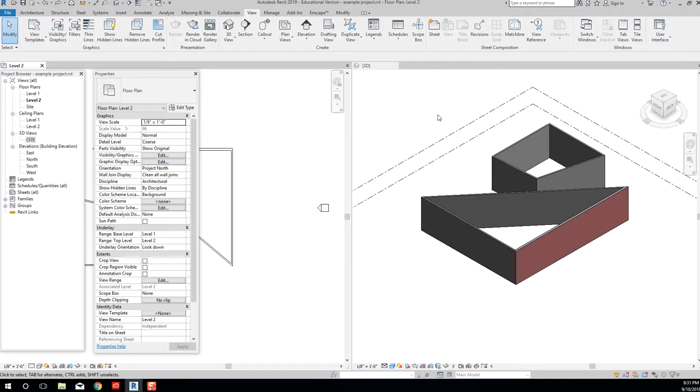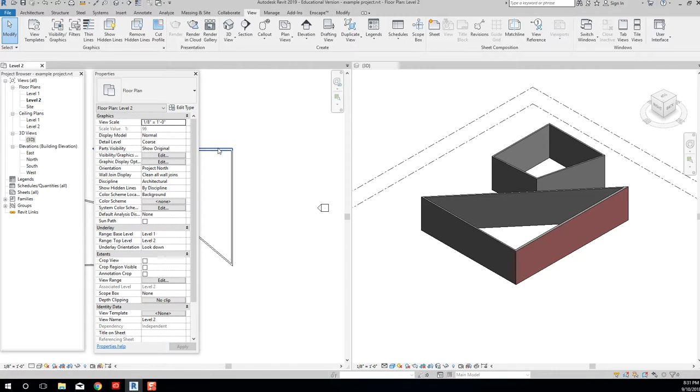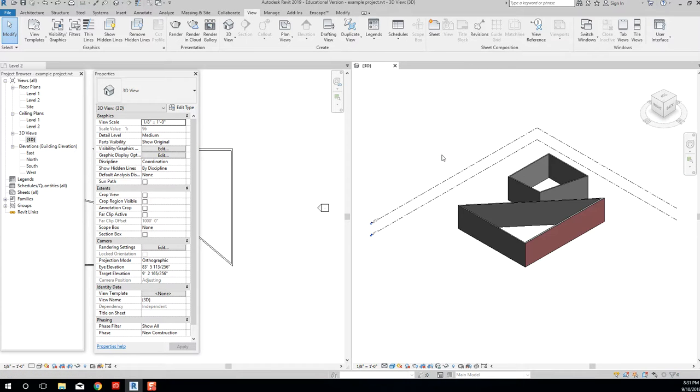The keyboard shortcut for zoom extents: if every now and again you double click your middle roller and something is catching or something weird is happening and you want to abandon your mouse and use your keyboard to zoom in or out, I can type ZE on my keyboard and it's a zoom extents. ZE, zoom extents. Okay. I can come over here, zoom in, ZE, zoom extents. So if your mouse is getting caught on something or doing something it shouldn't, you can always use ZE, zoom extents, to zoom in or out.